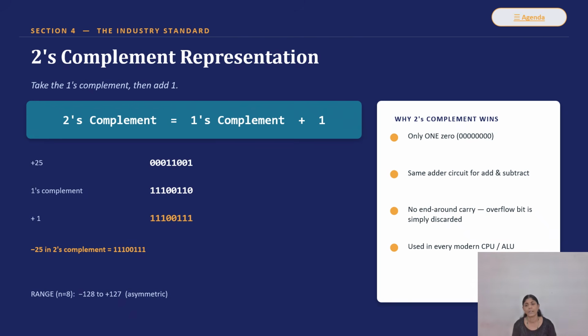Right? Okay. Why do we have to use the 2's complement? What is the first limitation in your sign magnitude? Plus 0 as well as minus 0. What is the problem available there in your 1's complement? Plus 0 and minus 0. But here there is only one 0. There is no positive value of 0 and no negative value of 0. It is only 0. So there is no sign bit here. Everything is only the magnitude.